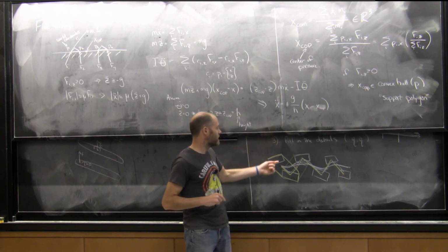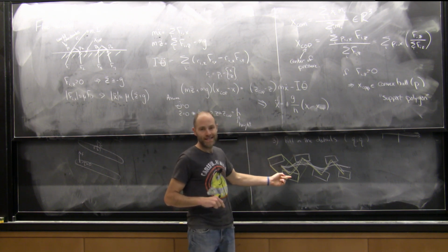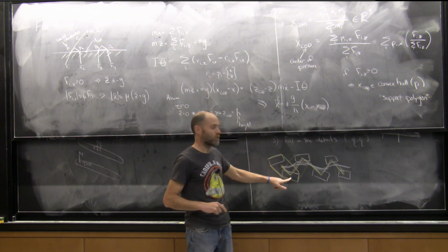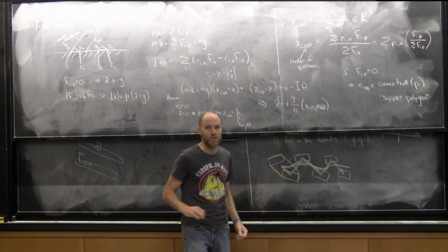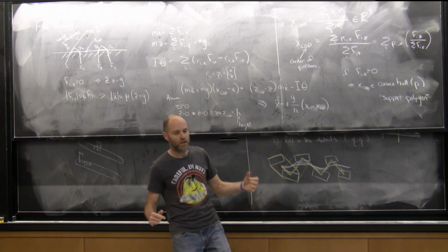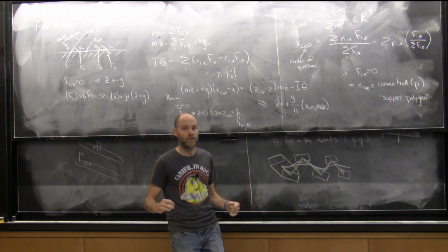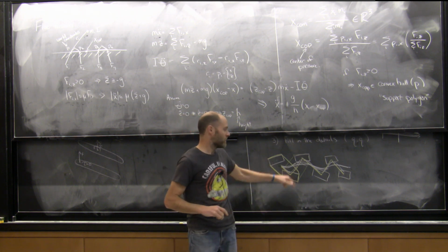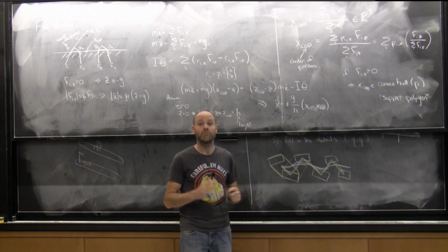This criterion of keeping your center of pressure inside the support polygon is less conservative than static walking. Center of mass inside the support polygon is static, or quasi-static, walking, which means that if I were to stop at any time, I would not fall down. With the ZMP, you're actually always potentially falling down, and it's okay. The ZMP gives you a way to plan that.